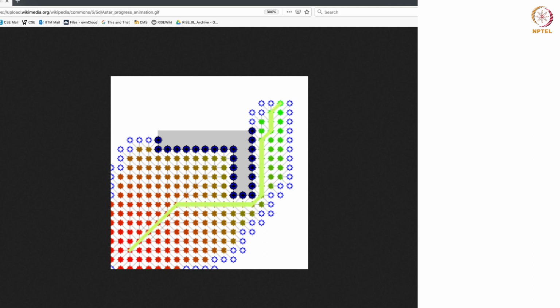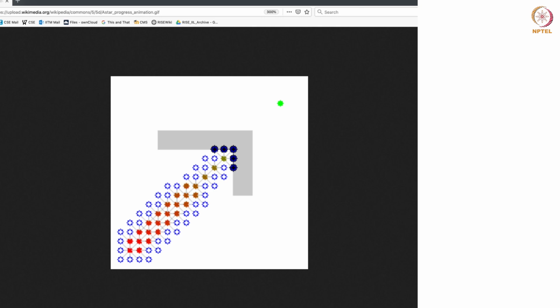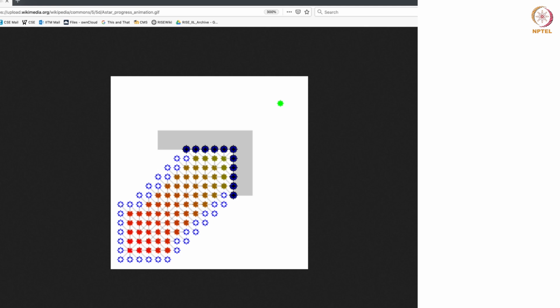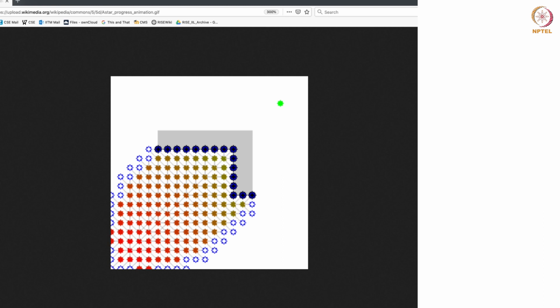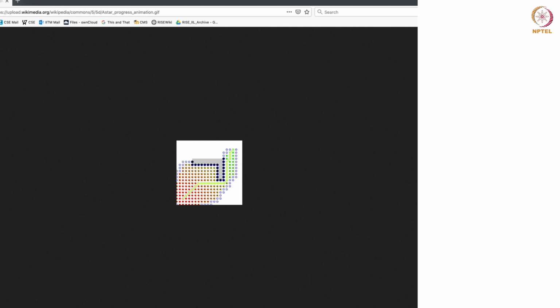And now after that, I'm just going to expand this whole region behind the obstacle. But once I got to a point, notice here, now I'm expanding the whole region that's blocked by the obstacle because it's still trying to go to the shortest path to the goal. Then once I reach a point where I get a direct line of sight to the goal, right, there's no obstacle here anymore, it will now only go through this path. That path stops and only this is expanded, and then I finally get to the goal, right, and this is the path to the goal, right.